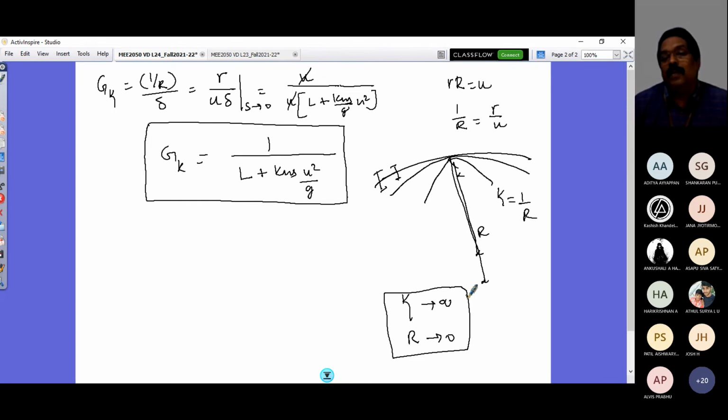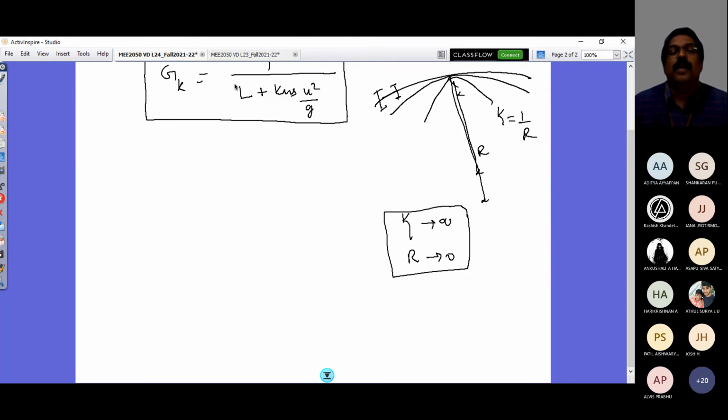So that would happen when your vehicle reaches its critical speed and the vehicle understeer coefficient is negative, and the vehicle is an oversteered vehicle. So for an oversteered vehicle, when you drive in its steady state motion at the critical speed, you would see that instead of going in a controlled manner in a given curvature, it would get into infinity curvature, and R tends to zero, and the vehicle would start spinning uncontrollably. So that's what you could see from this tendency, from this gain.